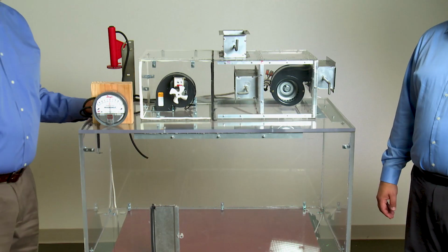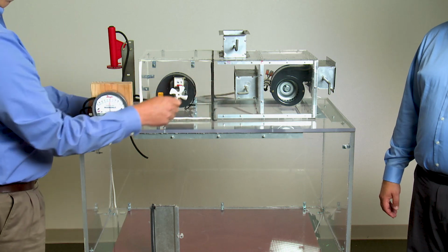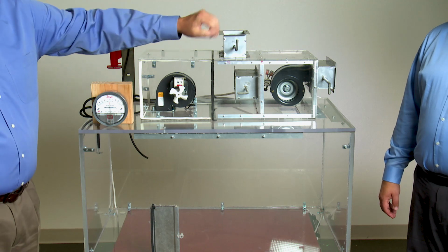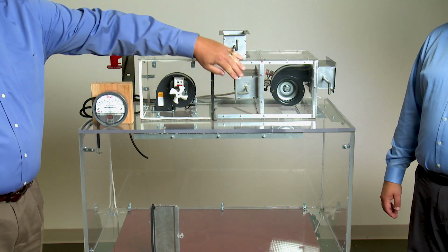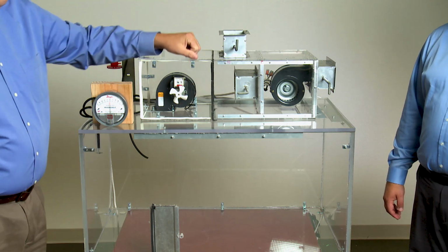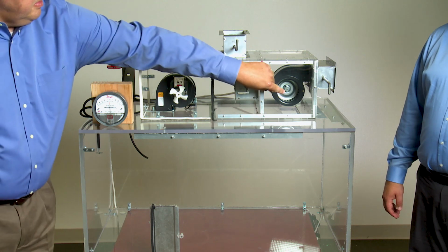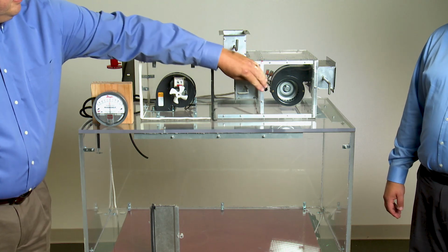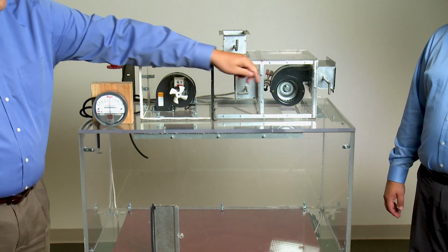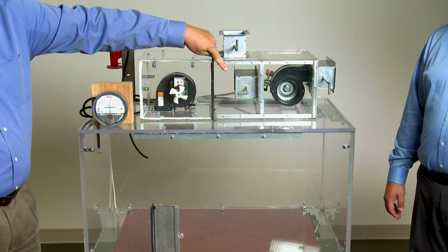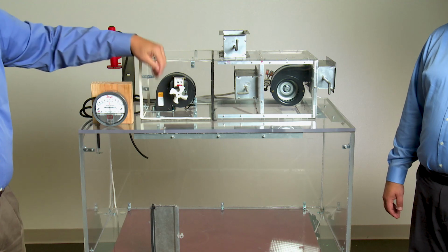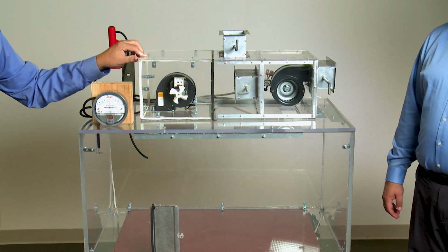Here we've changed this second module in our air handler, replacing the mixing box with this module, which includes an outdoor air damper on the top and a return air damper here inside. But now this one includes a relief fan that can blow air back outside the building. Return air is drawn out of the building into this chamber. Here the air then either recirculates through the return air damper or is blown outside by the relief fan. The recirculated air mixes with the outdoor air in this mixing box and is then drawn into the supply fan for delivery to the building.